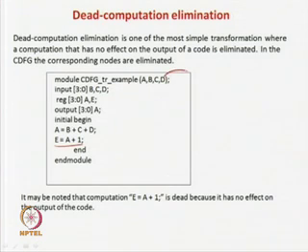He might have thought that E is another output. In this case his output should be A, and he could have thought that E is another output, and then he wrote this line E equal to A plus 1. But after some time he might have changed the specification and found out that the output A is enough, and the second output is not required. So he eliminated the value of E, but he actually forgot to remove the definition, and still he has defined register E.